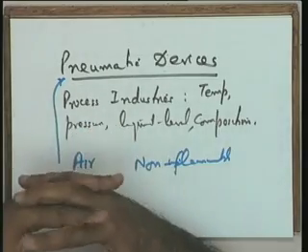Viscosity of air is negligible compared to that of hydraulic fluid, and the viscosity of the hydraulic fluid changes with temperature, and hence the performance of the hydraulic devices may change with the environmental changes. In this particular case, fortunately, that situation does not occur because viscosity is negligible. So, everything is really not rosy about the pneumatic devices, there is a problem.